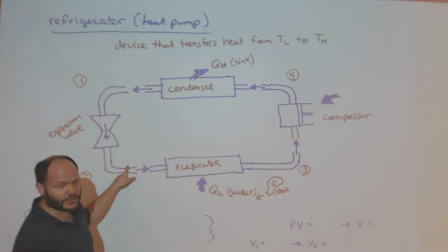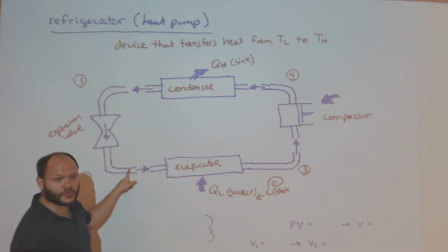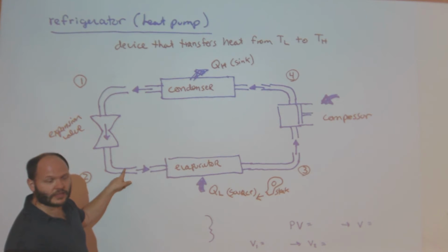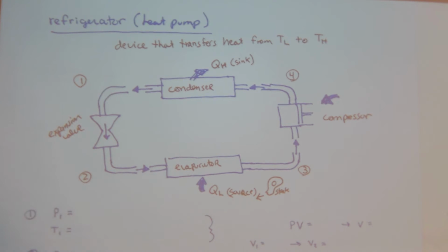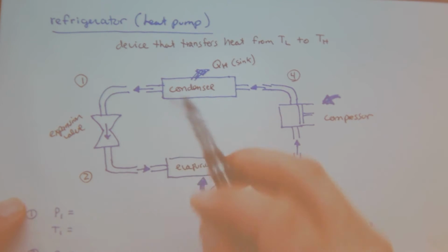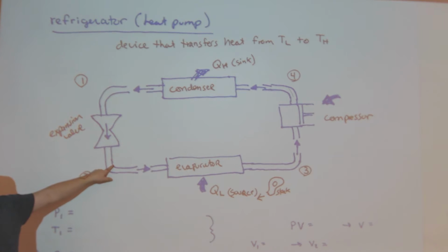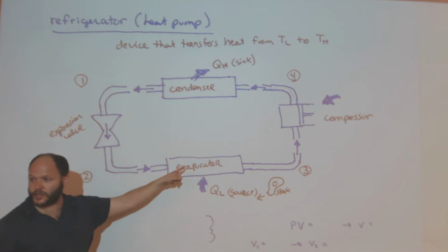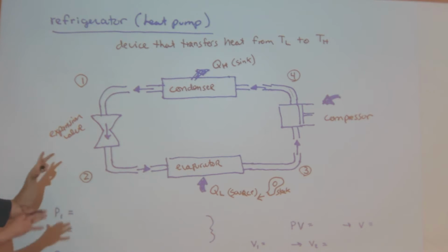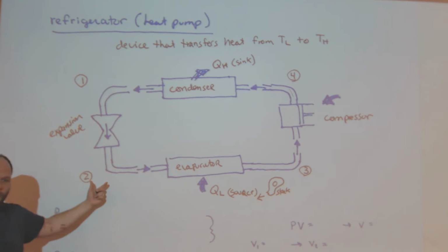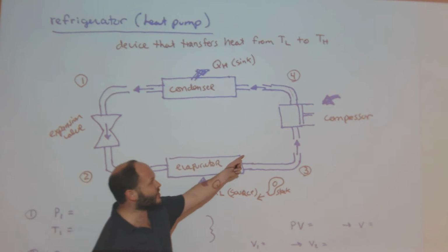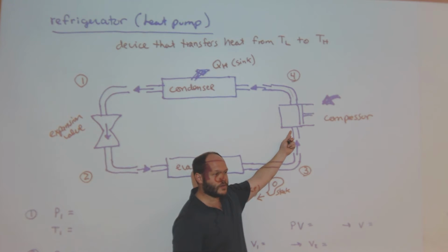No, really, that was with the turbine. Here, I'm not going to be going to superheated. I could just be going to a saturated liquid. Then I have an expansion valve, and I condense it, compressor. So if you open up your refrigerator or an air conditioner, it has a very similar type of subsystem. In refrigerators and air conditioners, the compressor is the part that usually goes bad first, and when it starts making really loud knocking noises, your compressor isn't working properly.